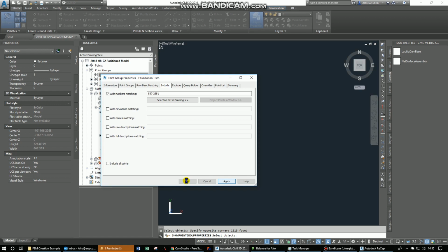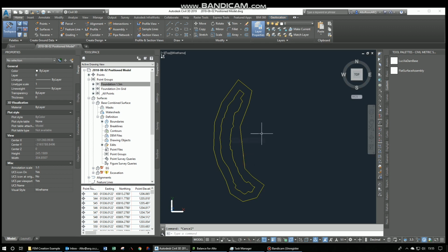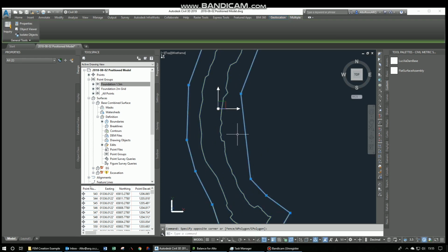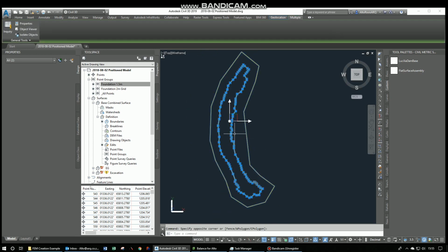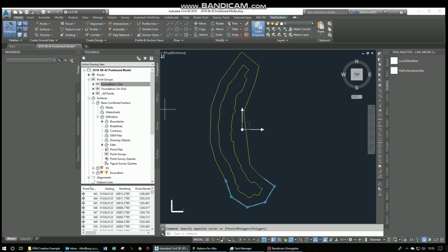I'm going to continue with this process, basically expanding the boundary, adding more points, increasing the grid spacing the whole time to have the model less refined the further we go away from the actual structure. And I'm not going to show that to you, since it's basically just a repetitive process, and that should be clear either way. One thing I neglected to mention is that for the next boundary set, you will use this boundary as the hidden boundary, and then obviously offset this polyline by, let's say, another 10 meters.